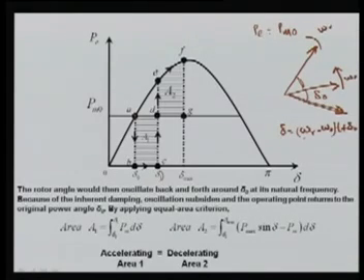If your machine is accelerating, this is increasing, this is your synchronous speed. So this term is increasing with time, so your delta is increasing. Here delta naught is any reference, it may be this, so delta naught will be 0. So once your machine is oscillating, your delta is increasing, and once it is decelerating, the angle delta I have defined is decreasing.